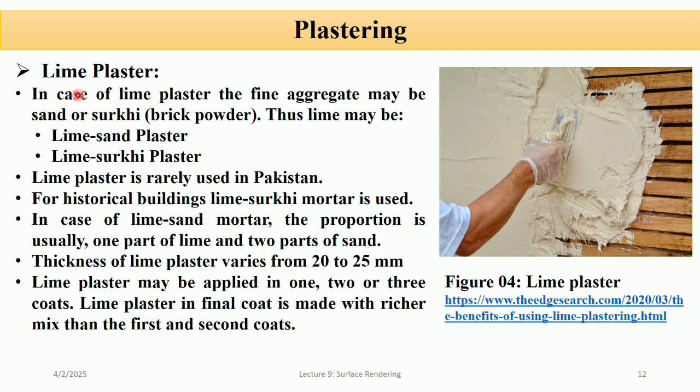So lime plaster. In case of lime plaster, the fine aggregate may be sand or surhi. Surhi is brick powder. So the plaster may be lime sand plaster or lime surhi plaster. It is rarely used in Pakistan, and the lime surhi mortar is used for historical buildings.